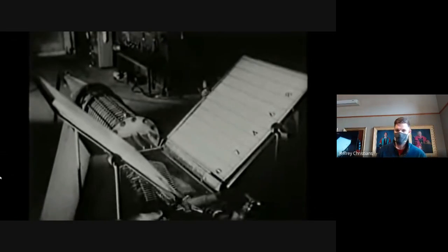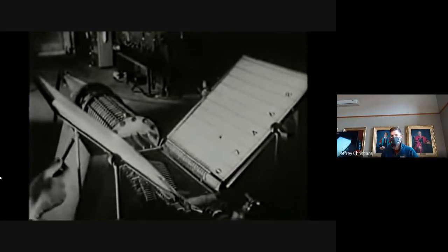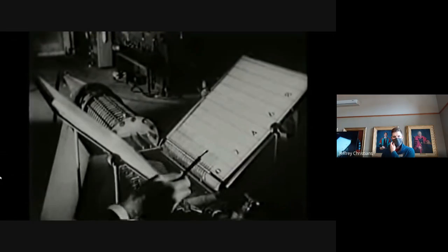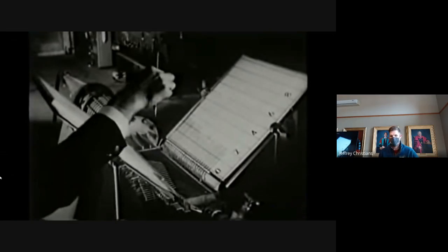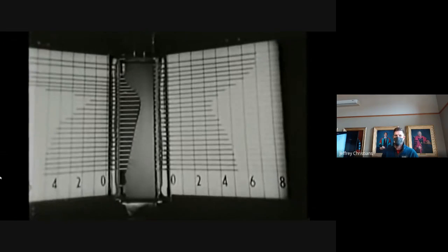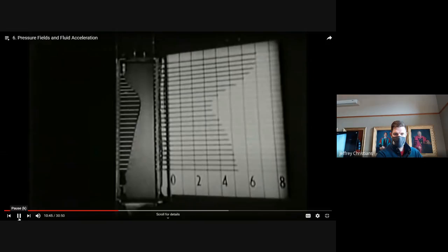Pressure distribution on the two walls. We will observe the length of the water columns looking down from a position directly above. Now the flow is steady. We will look first at the pressure distribution on the straight wall. Continuity tells us that because of the area contraction, the velocity increases to the throat.